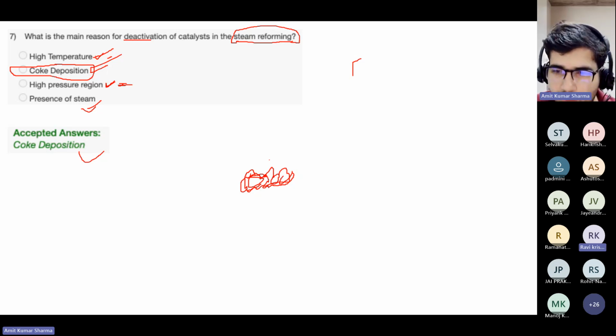Actually, the process is slightly different. It is suitable at lower pressure. If you're operating at 2-3 bar, it's good. And there are also DRI plants with steam reforming, where they operate at around 3 to 4 or 5 bar. So the process slightly differs depending upon the conditions.